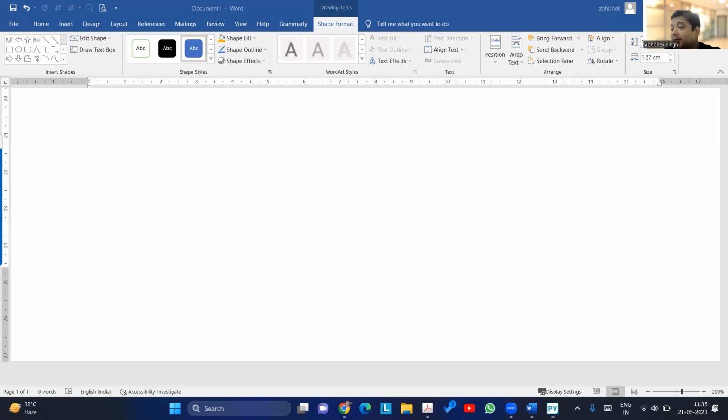And it will be very rare that at minus 78 the steel remains good enough; it's very rare that it will pass the impact testing. I have also not seen any carbon steel material getting used at minus 78.